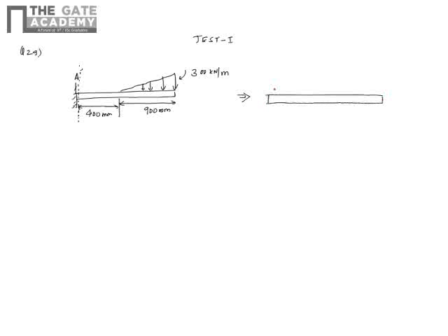concentrated load, and the way a triangle load is replaced. So let me draw a triangle. The way a triangle load is replaced, so if this is my L, so at 2/3 of the L I put an equivalent load, and the value of the equivalent load is, if the maximum intensity is W, it's basically the area of this triangle, so half WL.